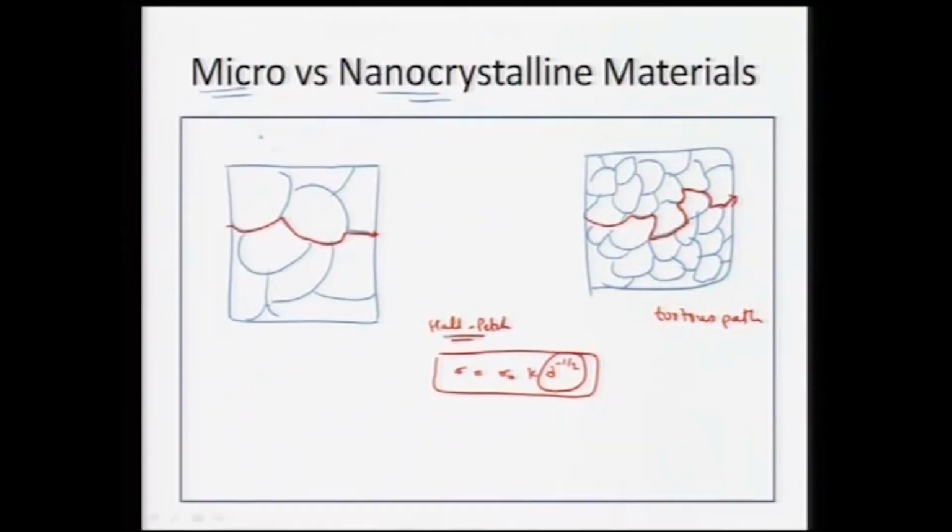So, we have a coarse grain, we have fine grained material. So, what eventually we are seeing is that in a coarse grained material the crack path is very easy, it can follow through very easily, whereas in fine grained material the resistance offered by the structure itself is very high, and also the strength of the material for deformation requires even enhanced strength because of its lower grain size.